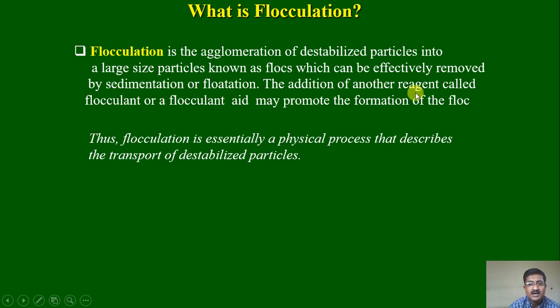The addition of another reagent called a flocculant, and a flocculant aid, may promote the formation of flocs, bringing together particles which is not possible in the coagulation process. Thus flocculation is essentially a physical process that describes the transport of destabilized particles.